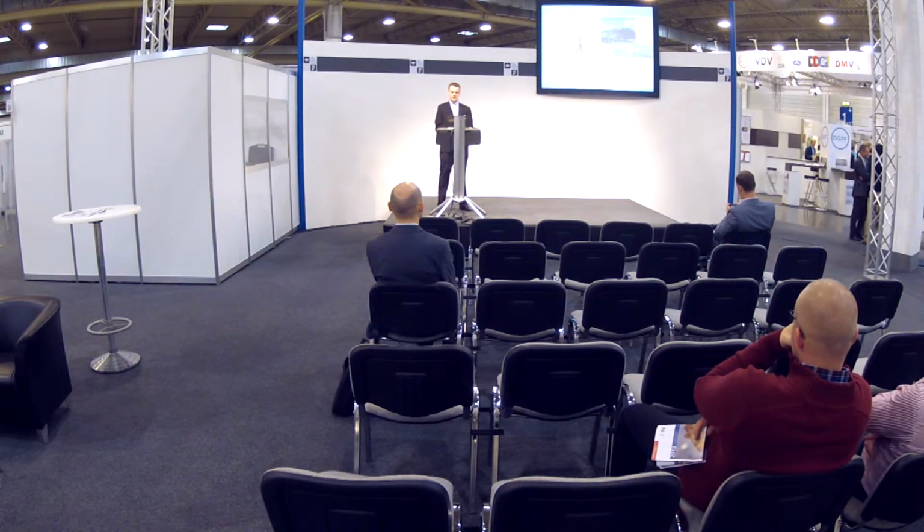It's easy to use, and we even operate in strong wind and even in rain. So this wouldn't be a problem for us. In one flight, which is about 45 minutes plus 10 minutes of safety reserve in the battery, you can cover at 1.6 centimeters between 70 hectares and 162 hectares. It depends on which overlap requirements you have. If you need a really good 3D model, you stay with the 70 hectares. If you only need a rough 3D model, you can do up to 160 hectares.